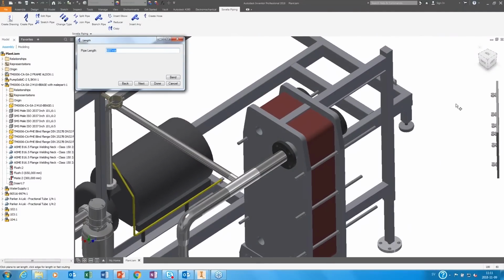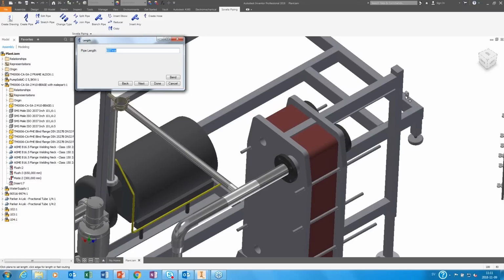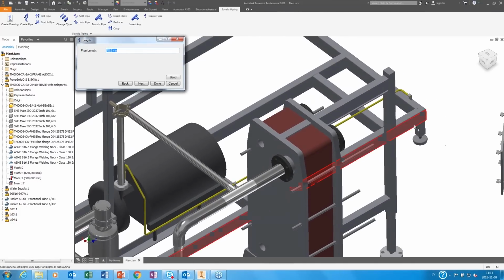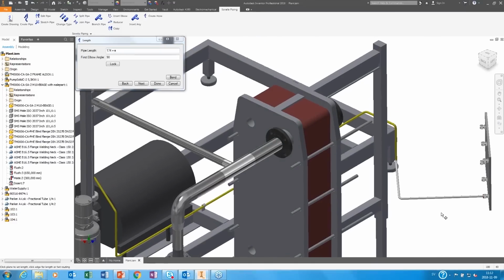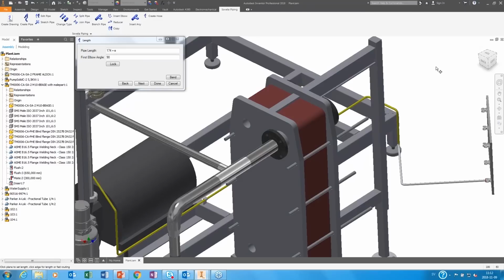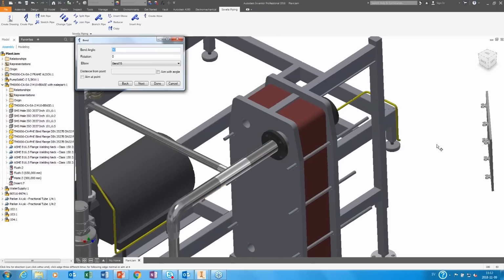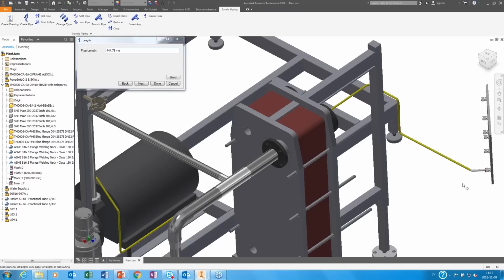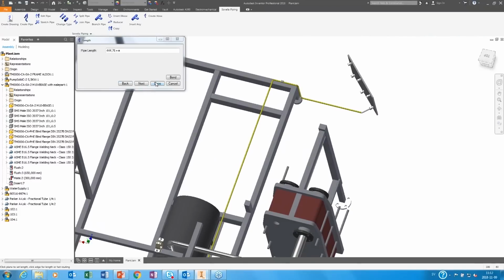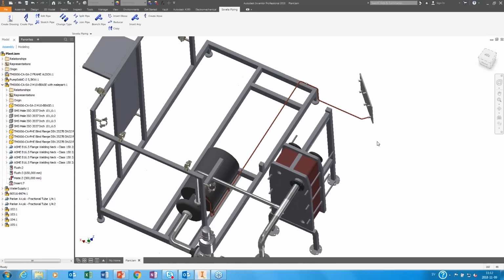or water tube. And I have another pipe holder here. So if I press Control, I can just go through that one and go to the frame and add maybe 10 millimeters so I get outside the frame. Next, I want to go down, press Enter, and now I want to go to this connection, but I don't like that way too much, so I just accept the length, and now I can choose the direction of the pipe. So I use the frame again. It should go 90 degrees from the frame. I press Enter, and now I can select that one again, and we got a nice pipe or tube.